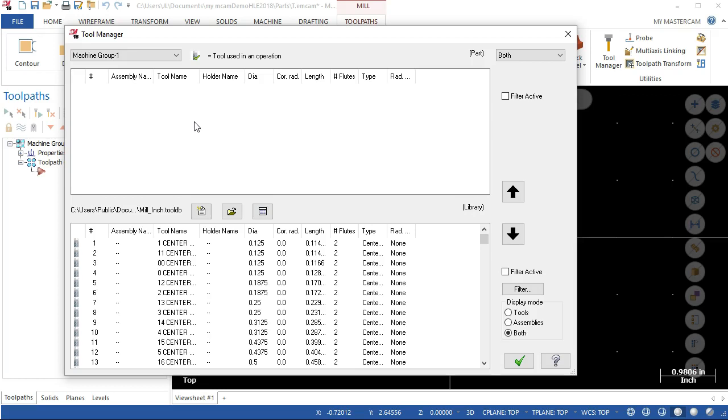All right, so with the tool manager, let's go ahead and set up as if we were doing a side mount tool changer, or we had a situation, the tractor type tool changer, where we're going to load up a certain amount of tools and even get into a situation where, as we can do tool checking, we would be able to replace tools within the group with other common tools of the same size and type.